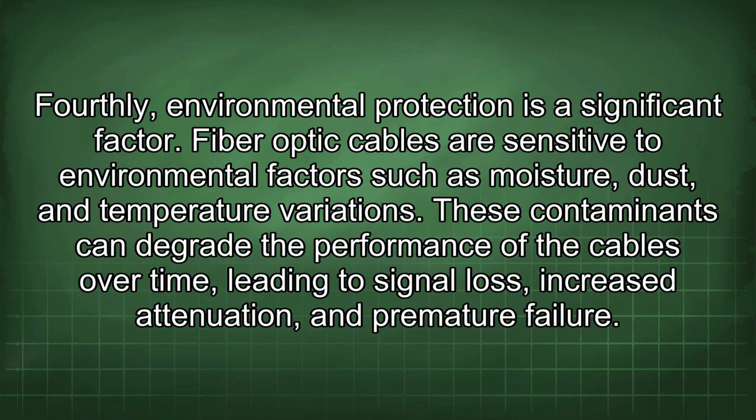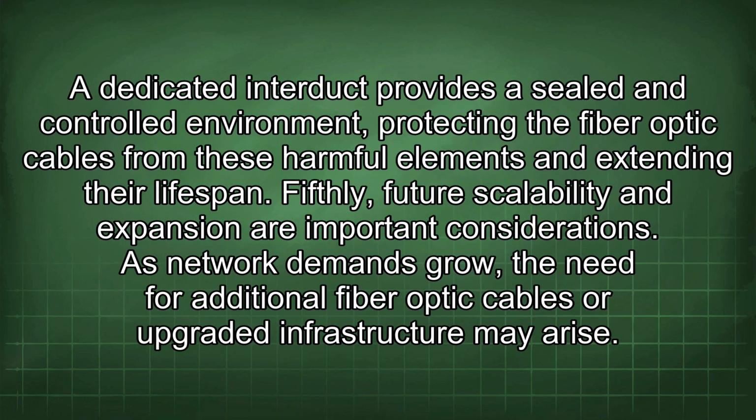Fourthly, environmental protection is a significant factor. Fiber optic cables are sensitive to environmental factors such as moisture, dust, and temperature variations. These contaminants can degrade the performance of the cables over time, leading to signal loss, increased attenuation, and premature failure. A dedicated interduct provides a sealed and controlled environment, protecting the fiber optic cables from these harmful elements and extending their lifespan. Fifthly, future scalability and expansion are important considerations.